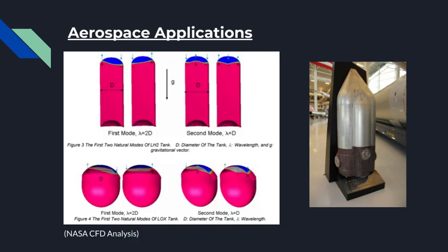In the aerospace industry, even the evenly mixed fluids can reduce the potency of the propellant and cause air to be injected alongside it. A common issue with propellant sloshing is that it can cause unwanted pressurization and depressurization of the propellant tank due to varying wall temperatures coming into contact with the propellant and causing the liquid to be away from the injectors. This is commonly mitigated using ullage motors to force the propellant to one side of the tank.